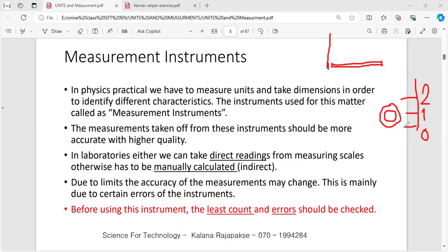What is the problem? Now, if I put the 0 of the scale starting from this part of the pen tube, the second unit is going somewhere in here, the first one is going somewhere in here, right? Now you know the measurement is more than 1 millimeter. The outer diameter of this pen tube is more than 1 millimeter, but it is not 2 millimeters.